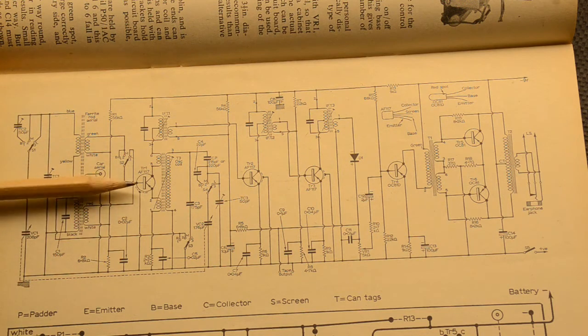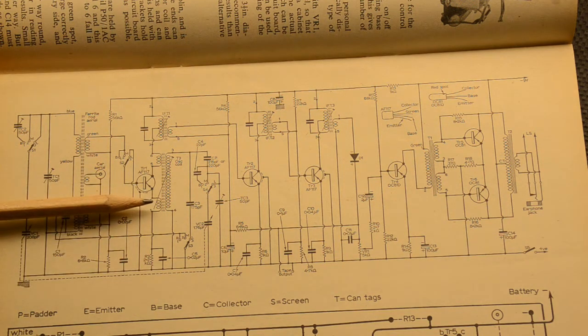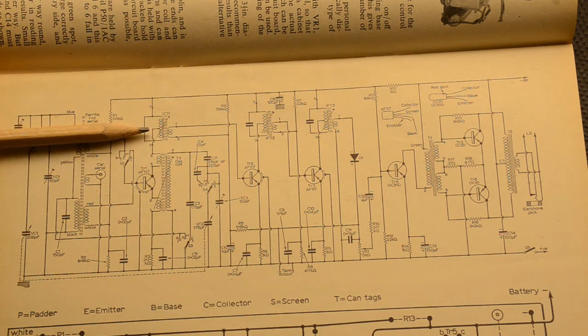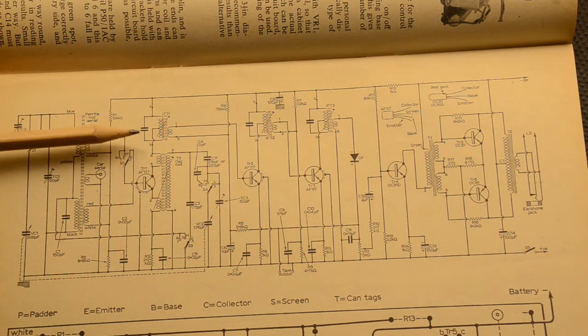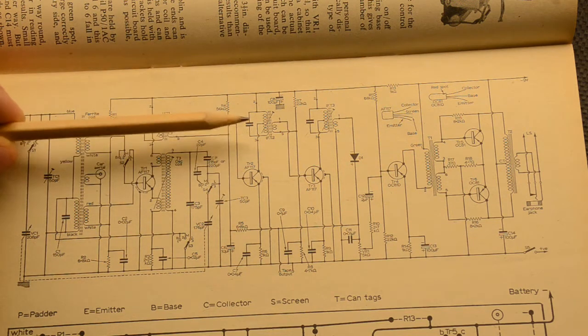This is fed into this first transistor. This is the oscillator mixer transistor. This actually does 2 jobs. It oscillates and it mixes the signal with the resulting oscillation. It then puts this out the top at a specific frequency, which is usually around 465 kilohertz, and it goes into the IF stages. It's coupled to the base of the next transistor, which then amplifies it again,